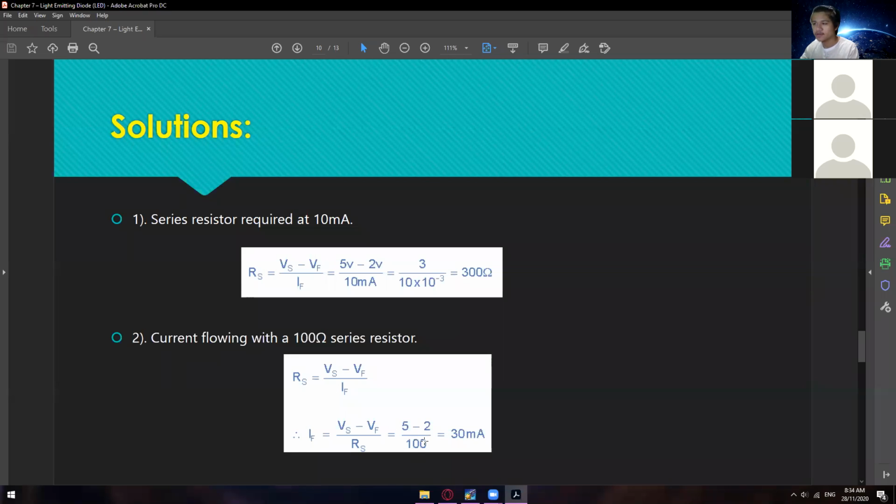So less than that or more than that is not within the range of the LED anymore. So take note, this is the safe point, wherein for us to be able to say that your LED will work longer, or its lifespan will be longer, if you have this range of resistors or resistance.